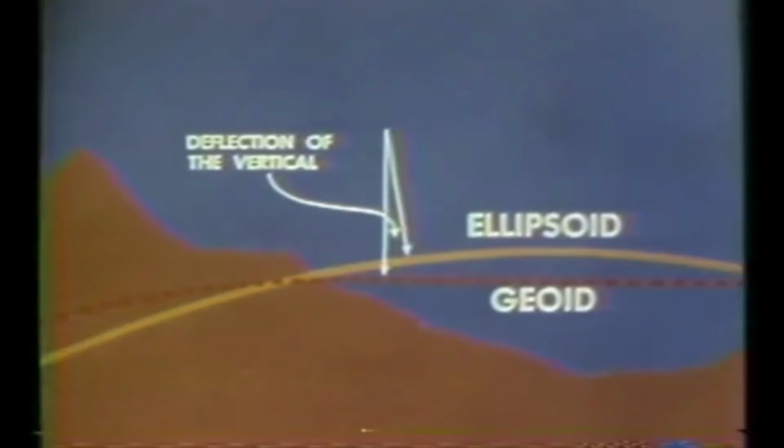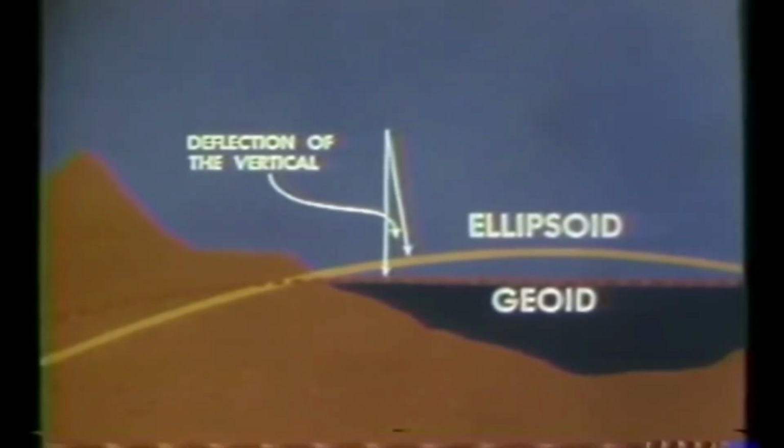Because sources of varying local mass attraction are provided by the Earth's high mountains and by the basins of the seas, the direction of the vertical, that of a plumb line freely suspended, is slightly influenced by such variations in the local attraction of gravity. The leveling bubble of a precision surveying instrument is affected in proportionate degree. By contrast, the observation of an artificial satellite against a background of stars provides a system of measurement that can be tied to the surface of the Earth, but which is entirely independent of the varying direction of the vertical on the Earth's surface.